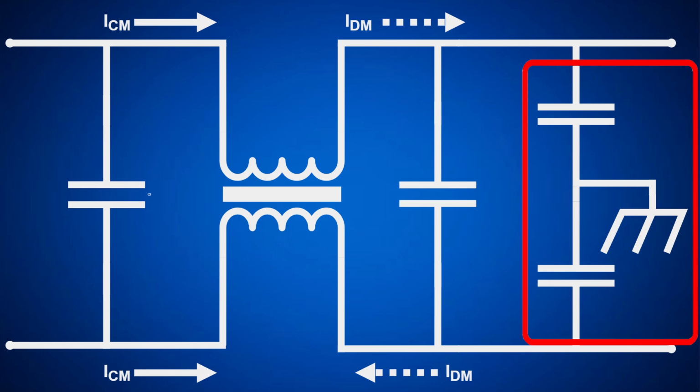This is actually why in some cases for high voltage circuits, you will see a capacitor that is placed between the high voltage ground and earth ground, because it is also trying to filter out the noise that is present on that high voltage ground line. And we're trying to make a low impedance pathway to earth ground to reduce our common mode noise.